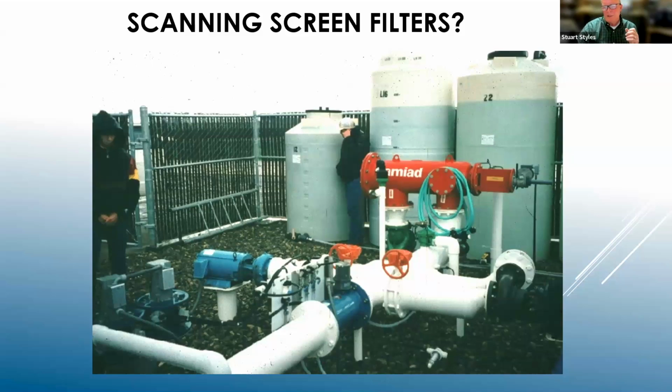I have used them here at Cal Poly on reservoirs, and we have 2 that have been out there for 30 years. As long as they're maintained properly, if we get the screens pressure washed annually and do a hot dip or the chlorine dip with them, they've been working all these years, and we haven't had to go to a higher filtration level. But the application that those go to is sprinklers, so they don't have the small particle size requirement that we would have with drip, and so we've been able to get them to work in that application.